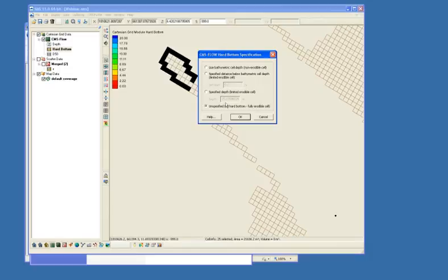And so there's different options here to specify that. So if you know what the depth is for that rock to be located, you could specify some value here. And the default value here is the average depth of every cell that's given. But that's normally not what we want.